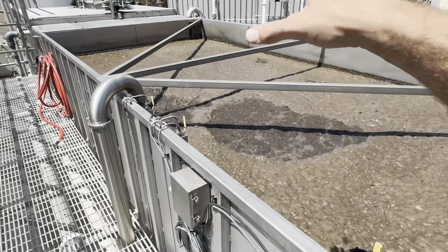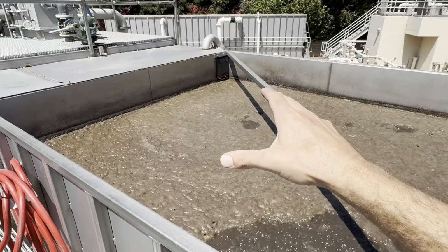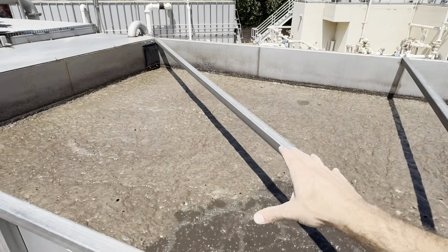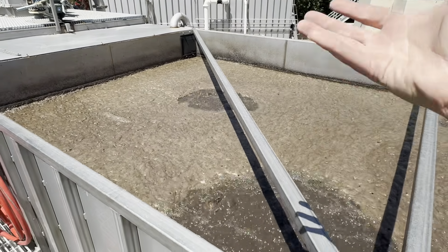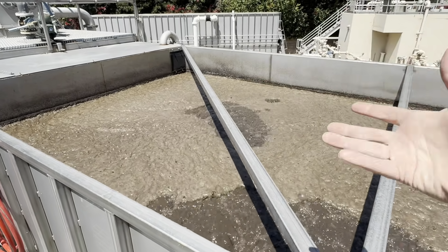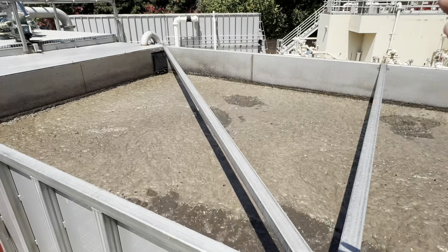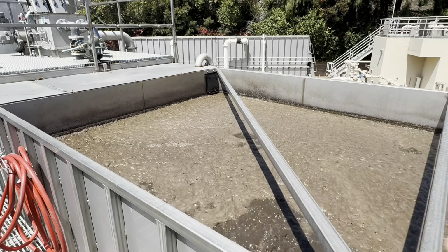So anyway, at the beginning, as the influent comes in, ignoring the anoxic zone, what's going to happen is these diffusers are supplying oxygen. We're going to go over this on the whiteboard a little later. They're supplying dissolved oxygen to the aeration basin, and these microorganisms are uptaking it. And remember, BOD is the biochemical oxygen demand that the wastewater would put on the environment.